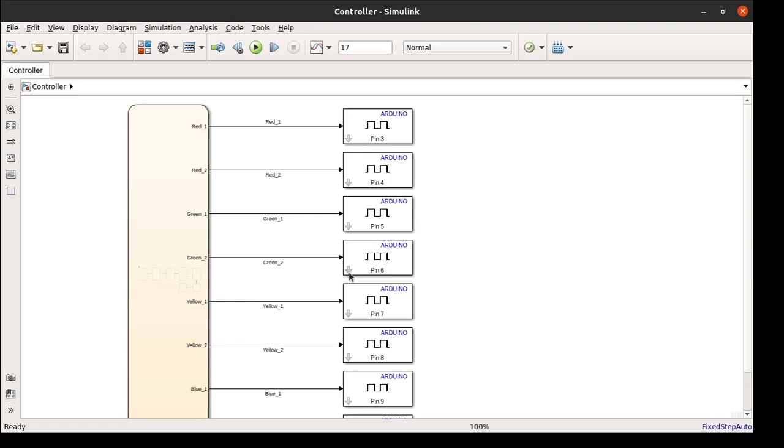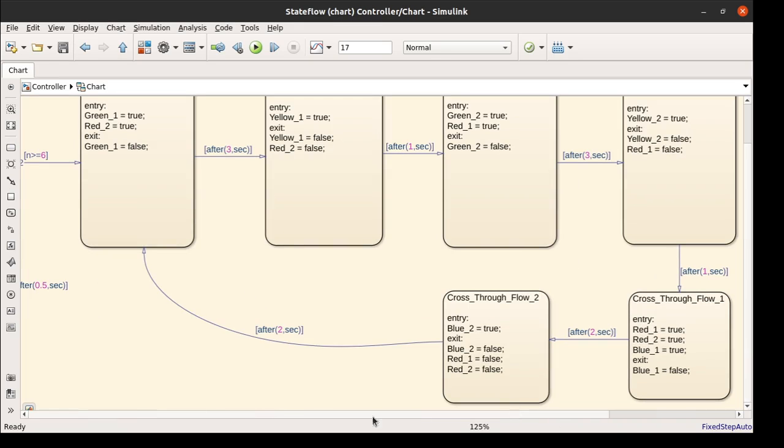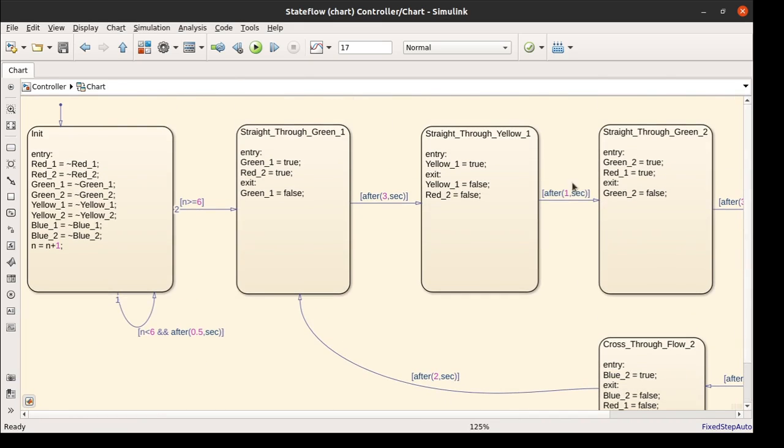This is our earlier model we have developed using the state flow. This is a plain traffic simulation without any variable delay by the user. Now we want to incorporate the variable delay. So for that, let's go and change each multiplication with some new variable called delay. Now let's apply the same concept for each of the multiplications.